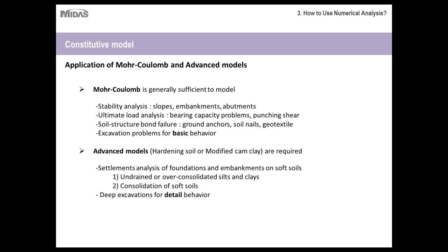Another area where these advanced models are required is if you want to do a detailed analysis of deep excavation with detailed behavior. So the difference for this particular session, since we are looking at deep excavations: if you have to do a basic analysis or a basic behavior representation of excavation, Mohr Coulomb would be sufficient.